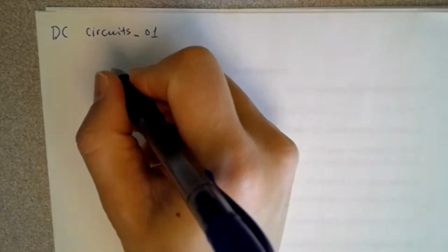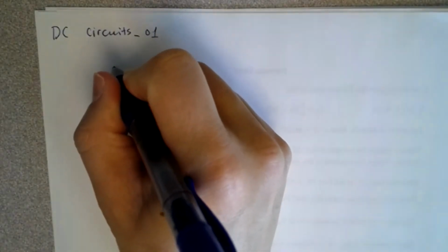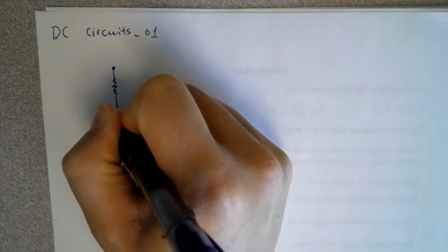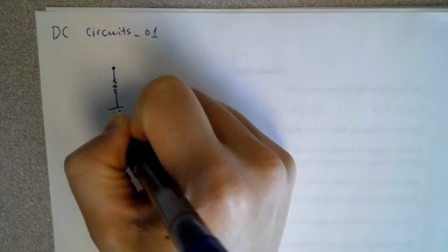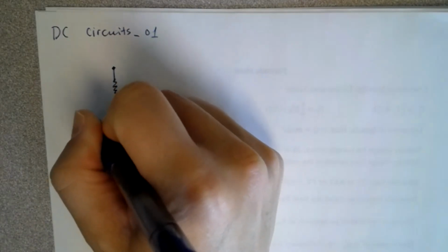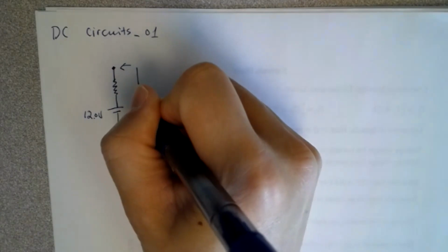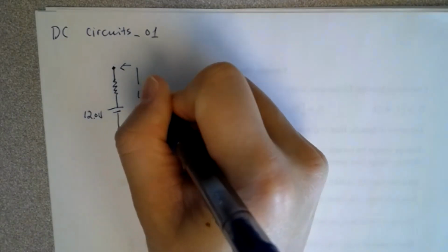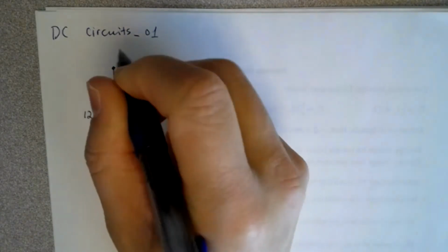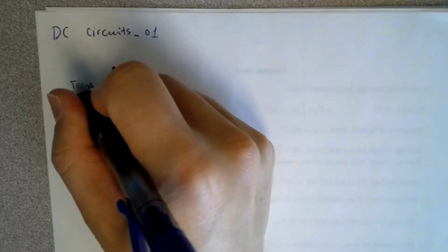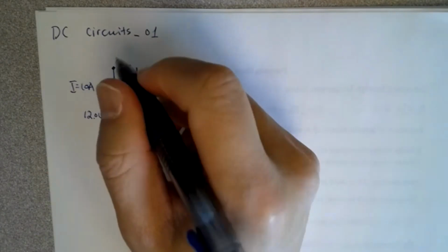So this is being charged, but here is the terminal. There's an internal resistance, and then there's this battery voltage, which is 12.0, but across these two terminals is 16 volts applied. As a result, there's a 10 amp current, and it's asking you first for the internal resistance.